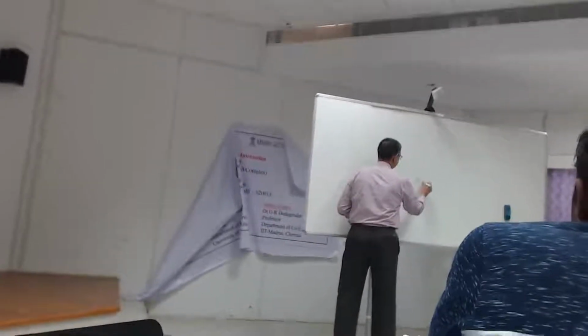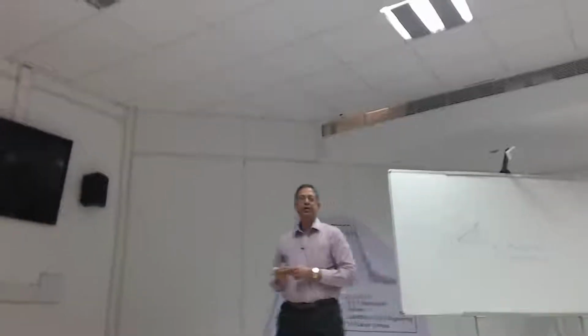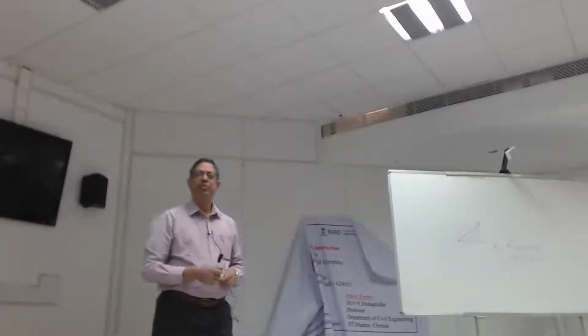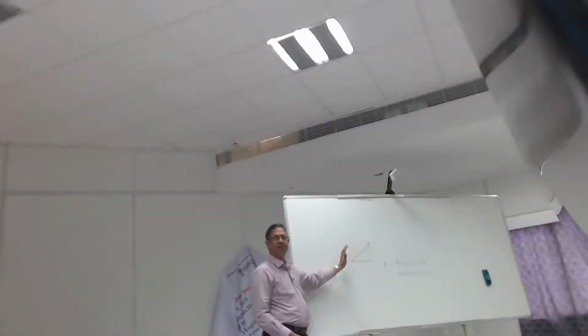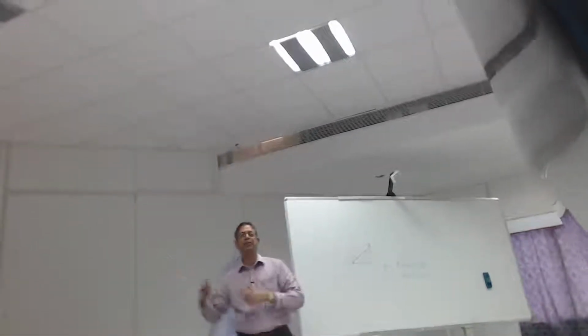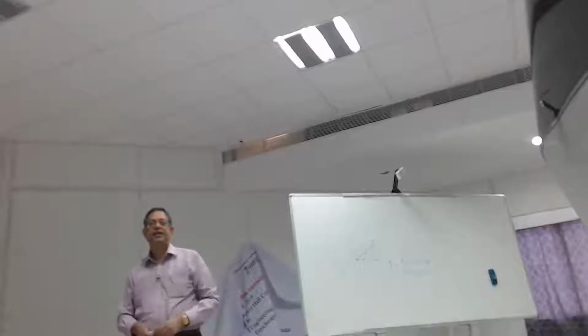the area of the loop over the area of the band. And this works fine for soils. Because our material, even with the pore pressure generation, has these loops changing all the time, we can work out cycle by cycle how damping is changing.